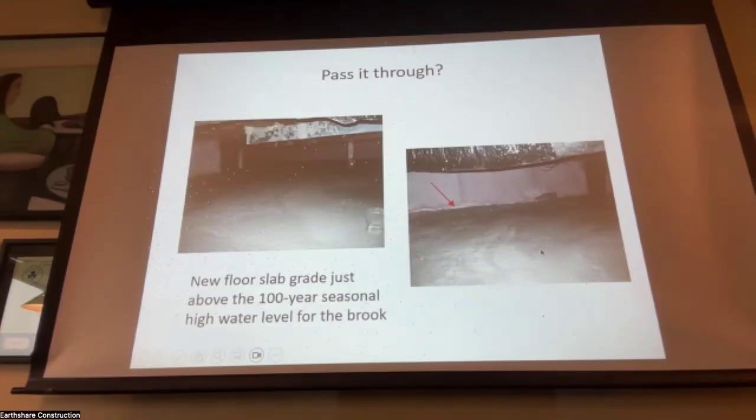Fly ash is the cheapest concrete you can get. We just wanted fill volume, fill that we could pump. And this was very successful. I told them if we run the tests on this and the humidity's still high, we'll put a sealer on the concrete, but we didn't have to do it. We tested all these crawl spaces for humidity.